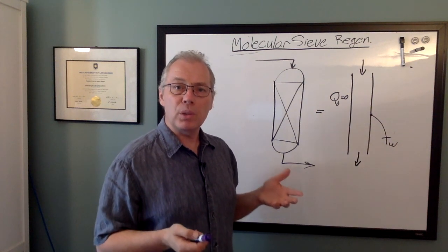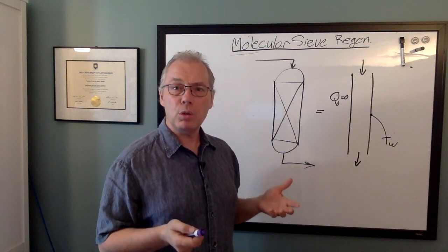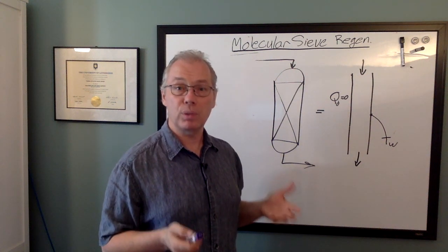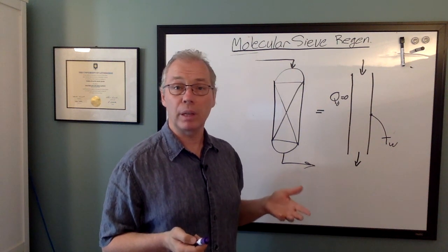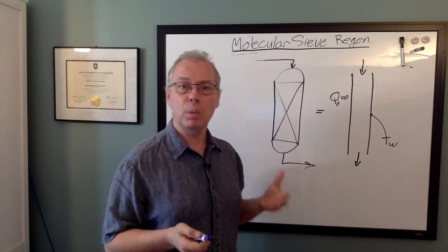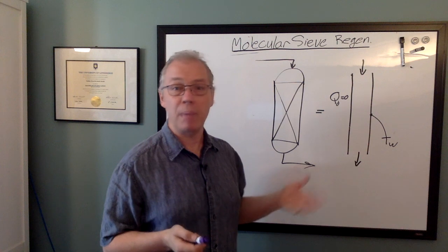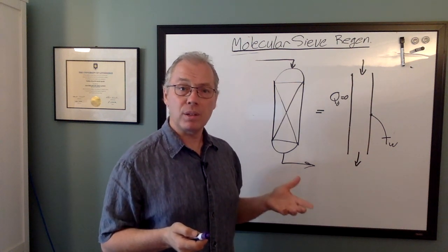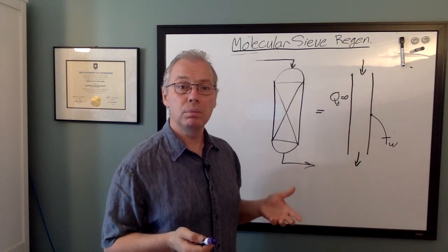The great thing about a CFD simulation is that we can try out different light-off sequences to find a method that reduces the flow disturbance to the online molecular sieve bed. And if a simulation looks promising, then we have good reason to convince the plant manager and the operations manager that a plant test should be tried.